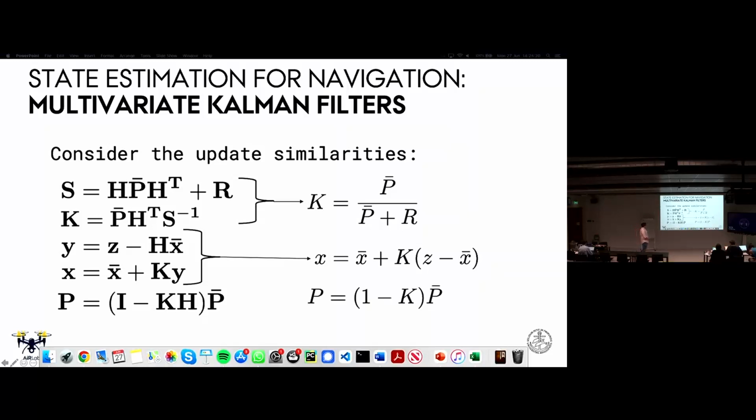Same thing here. You can see the residuals, and you can see the updates for the states. Again, the Kalman filter is being used as a residual. The residual itself, I kept as a one-liner, but you can basically see that we could have a variable called y, and that y would then be used to subtract the measurement from the state space, and the same thing for the covariance. Now, I obviously is the identity matrix, which is a matrix of diagonal ones.